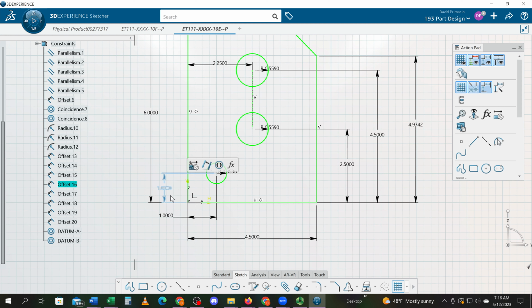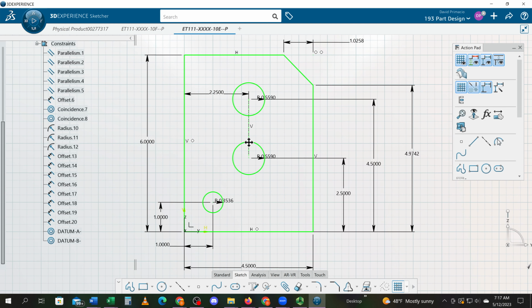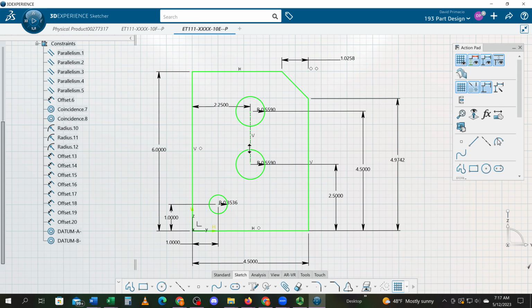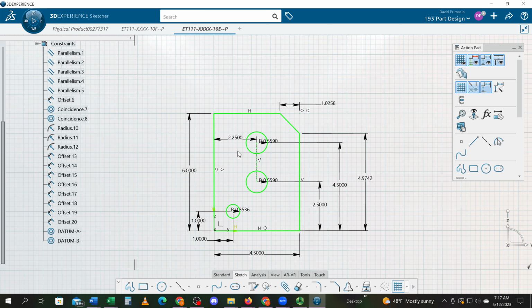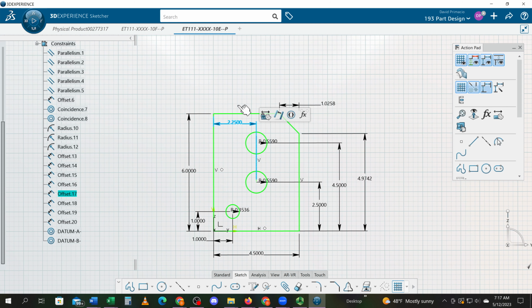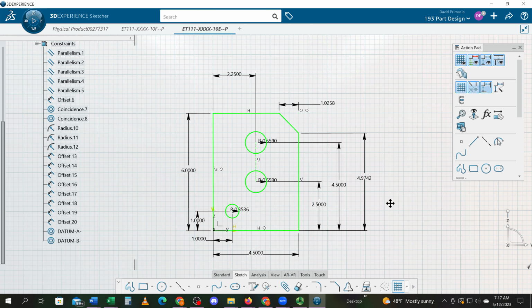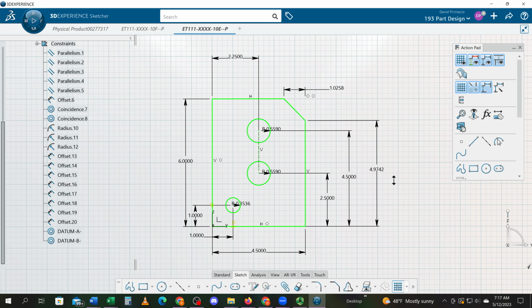That should stay centered. Okay, this 0 shouldn't be any closer than a half inch to that part. You want it nice and spread out so people can pull this up and see it and read it. Now what's nice about this is every dimension on here should match, or every dimension on here is fully constraining this part. When you do your drawing, these are the exact same dimensions you would want in your view.